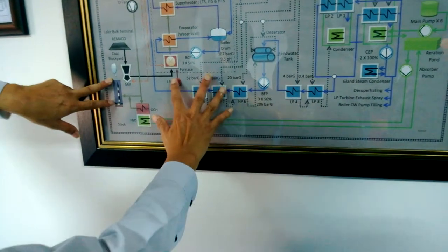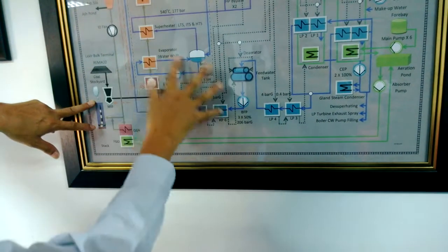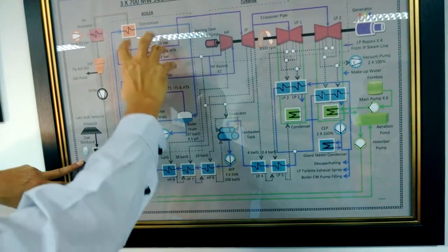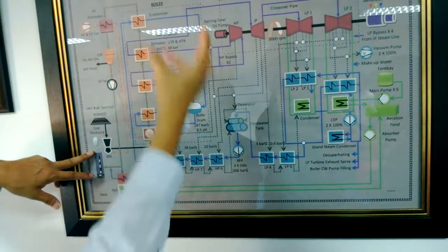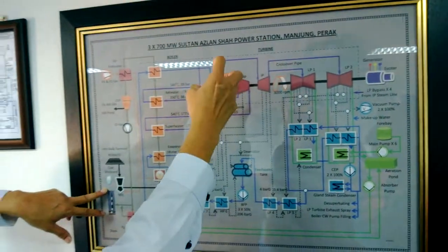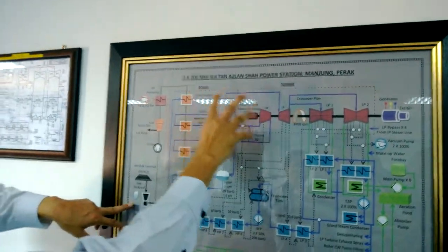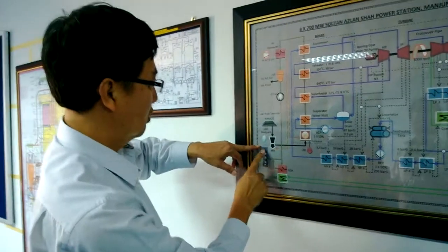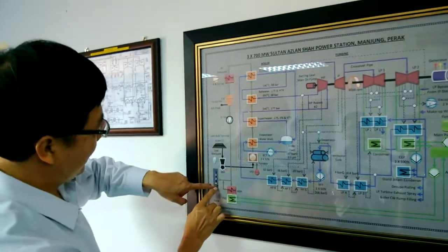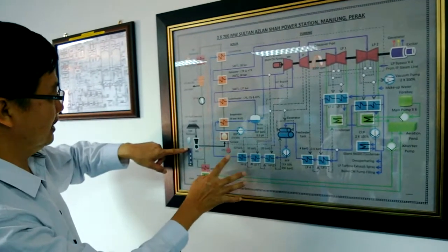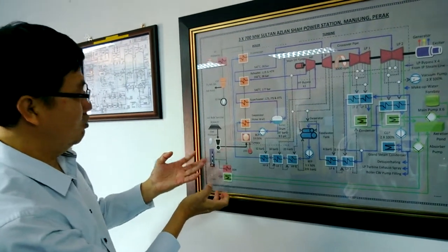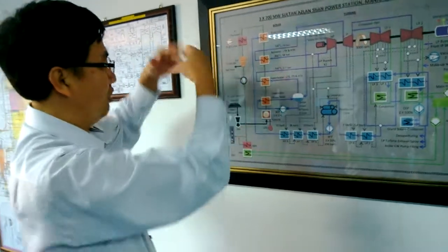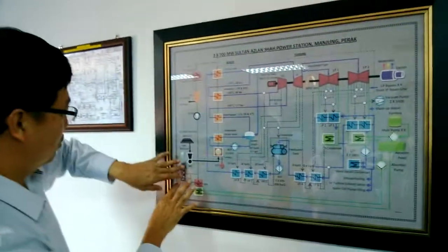So in the boiler, when we blow in the fuel and the fuel gets burned, the flue gas, with all the coal dust, comes up, and then we extract heat from the gases, and then the flue gas will come out through our tube. We call it the stack. The most we can extract is until it's 73 degrees C, and if we extract too much heat, the gas cannot come out. It must be of a certain temperature to come out.